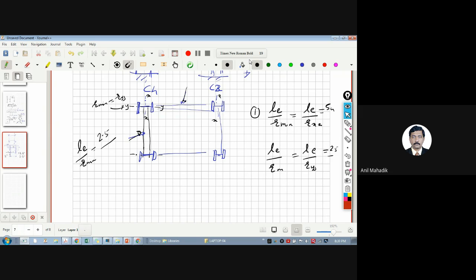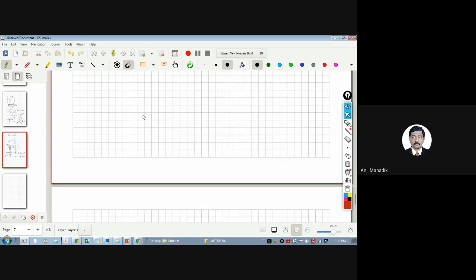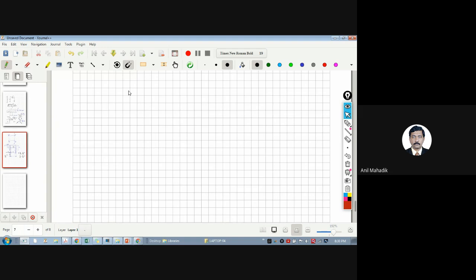Imagine that you are having a compressive force on this column, so let's take an arbitrary example again. Let's say this is a column in plan and you are having compressive force which is normal to the plane of the paper. So definitely in the direction of the minor axis, it will try to buckle. So this will be your buckling direction. Minor axis पे ही जाएगा ना buckling.